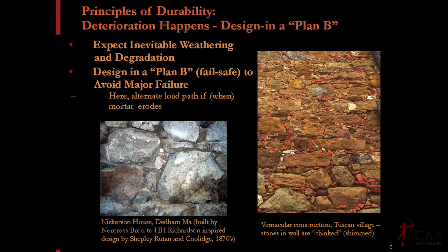And the reason this is really important is mortar is not that durable, particularly in a freeze-thaw environment. So when you have large stones like this, if they left all this space in between as just mortar, then when that mortar erodes, everything starts to shift around, the stones move, and walls start to bulge and get displaced and crumble and tumble out. And when this erodes, you've still got all this point-to-point contact to keep everything stable and in place, so it acts more like a dry-laid wall, and that way it becomes very easily reparable and maintainable and sustainable over time. Easy to keep that going.